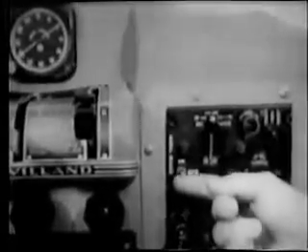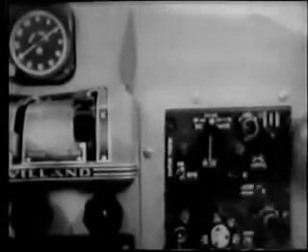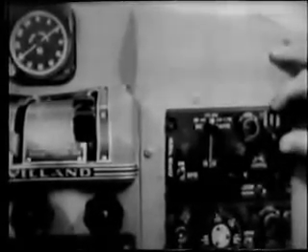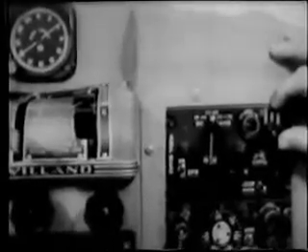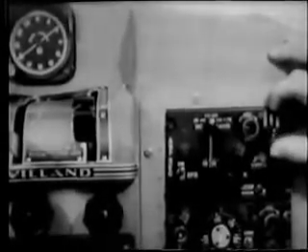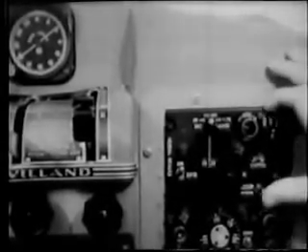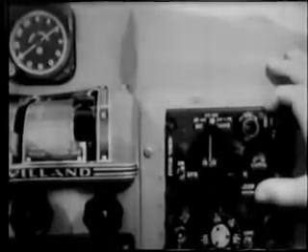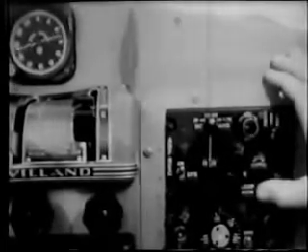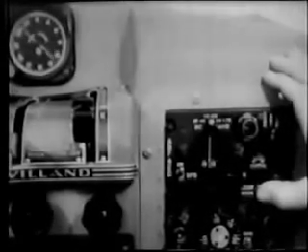The beat frequency oscillator is used for tuning when a station does not transmit a continuous aural tone. It is further used to establish a null with this type station when using the loop manually. With the BFO switch on, a tone is created within the receiver that builds or fades with the signal received.